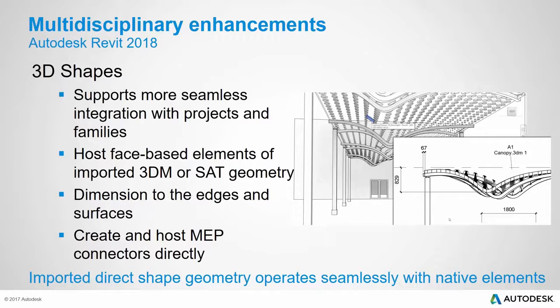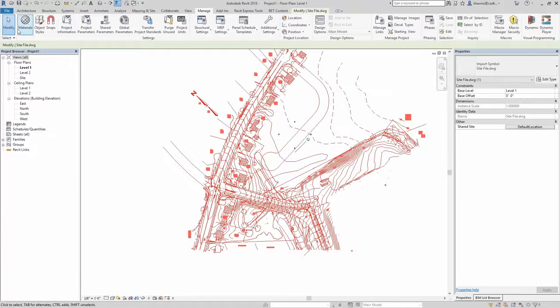Now, they're still not flexible, right? You still can't flex that imported geometry. It's not real Revit graphics, but there's a lot more control there where you can dimension off of it, ask it questions, and then leverage that for other information. In fact, quick example of this for you. I'm going to toggle back into Revit again. Let's see here. Revit 2018.